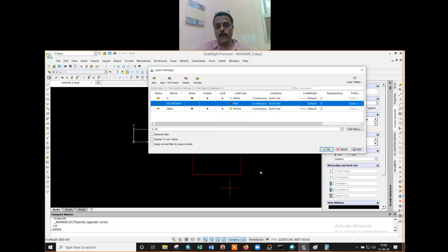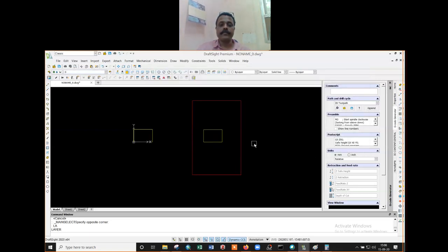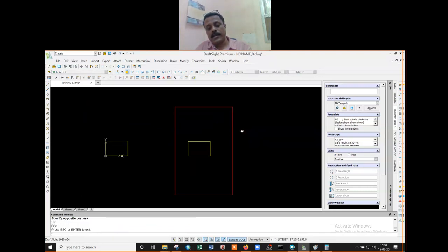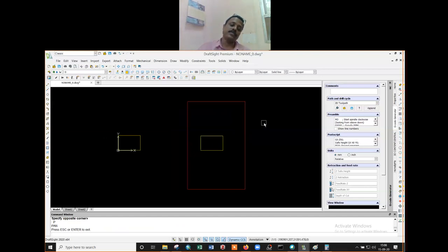Click OK. Now, I said that I want to change the line type of the boundary layer. For that, I will go up to here and then I want to show it as a hidden line. And OK. Now again, you click there and you see that my default here is by layer, that is the boundary layer, that's the color. The line type is dashed, but I cannot see the line type. Why? If I am choosing a dashed line type, I cannot really see it here. I think this is because of the scale which you are using.